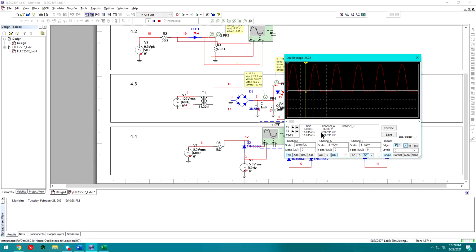So this is the forward voltage drop on the 1N4006. And that makes sense, right? Because it's connected in a reverse manner. So we're actually rectifying the negative half cycle, right? Now this is actually the negative half cycle where it goes up to the positive. And the positive half cycle is where it stops conducting. But it will only stop conducting once it gets to a threshold of 643 millivolts. It won't stop conducting before that. So that's why we have this slight dip under the zero axis.